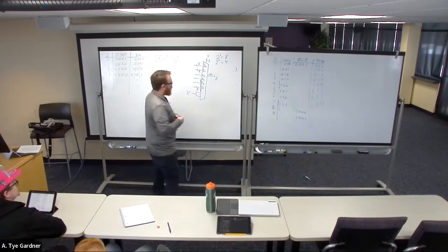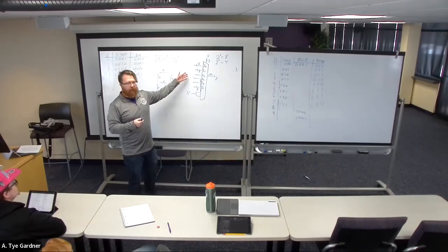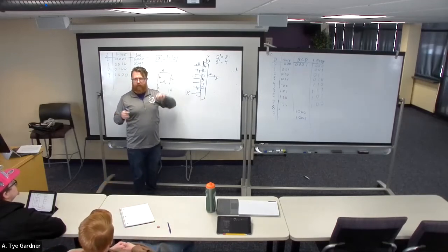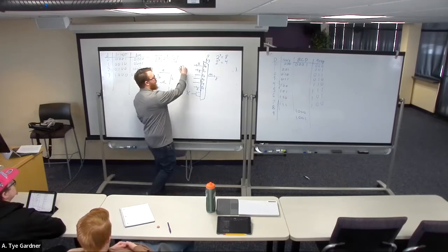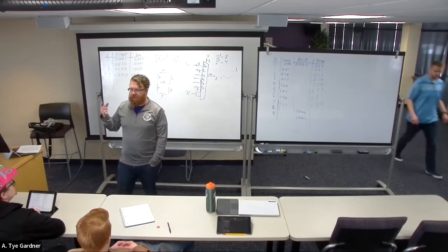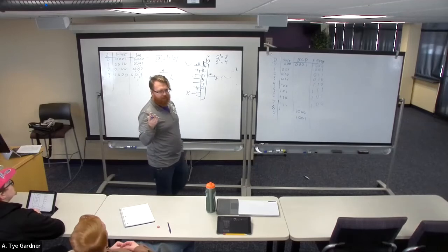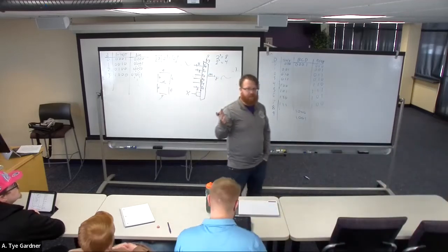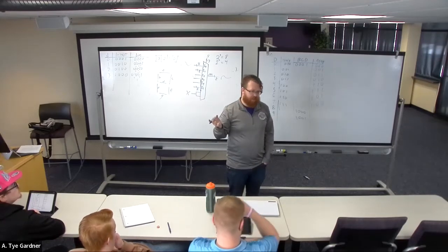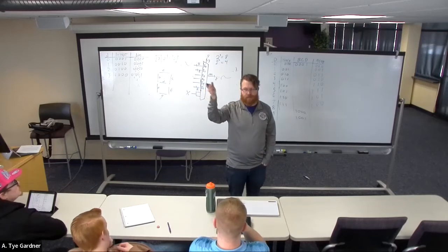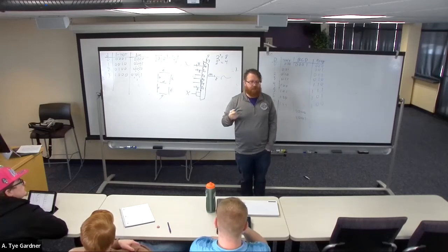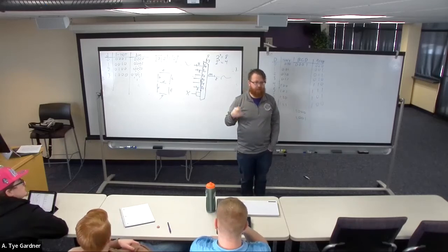I was designing a circuit once upon a time that was a MUX where each channel, rather than being a digital signal, was analog, right? We've talked about the difference between analog and digital. The analog signal would pass through if I chose it. And the analog signal was actually coming out of a rat's brain. It was a neural recording device. It had 100-something electrodes in its brain, and you want to measure what each of those electrodes is seeing, right? So you multiplex through and sample this one, now that one, now this one. Well, I wanted to do it fast because I wanted what's called high temporal resolution.